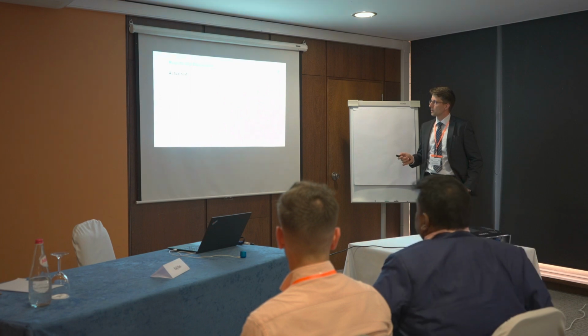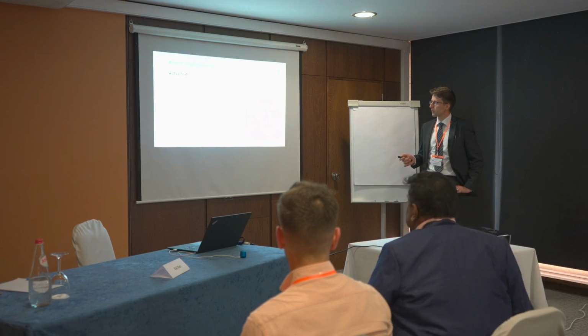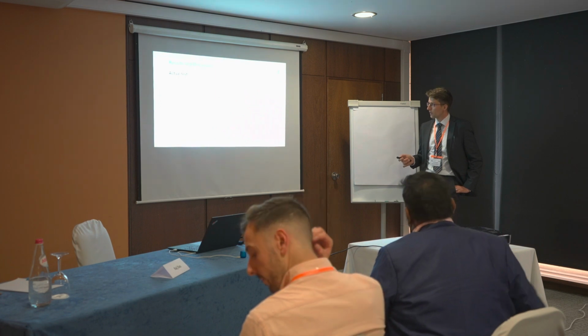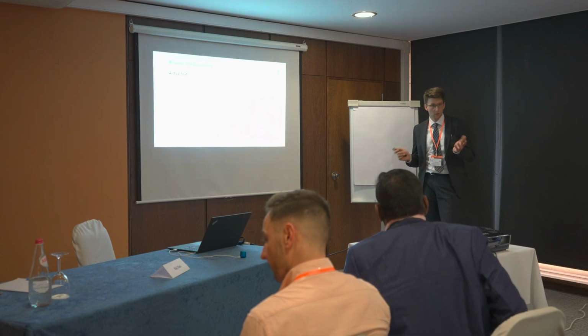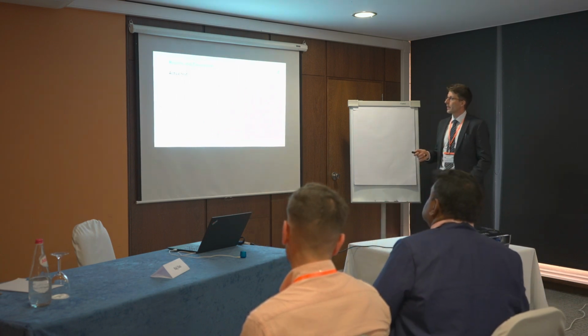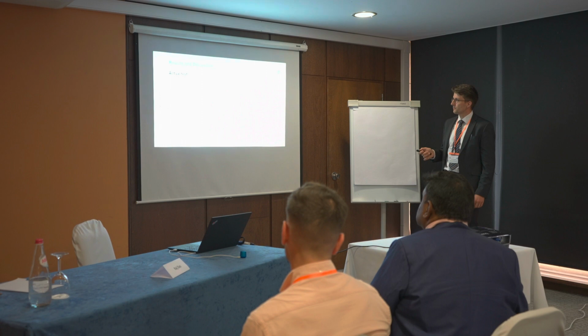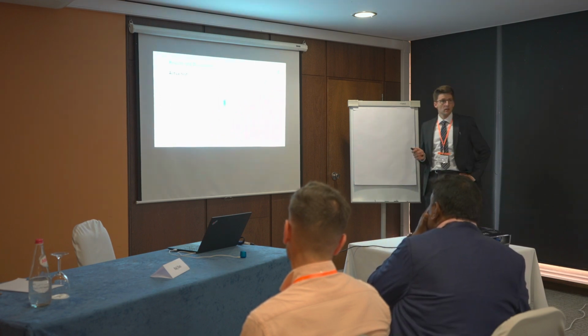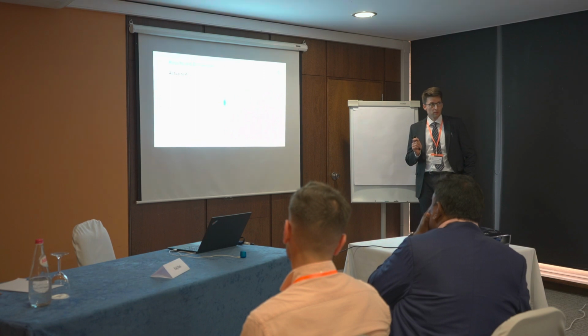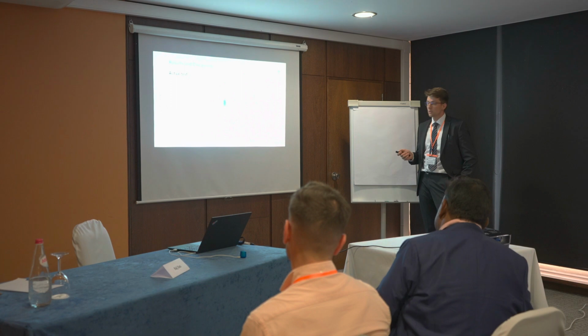Then we performed an actual test with the known calibration constants. We also use a smaller pulse shaper. We introduce this incident pulse. When we use a specimen, we of course get a reflected pulse and the transmitted pulse in red. And then we can compare the displacements measured by the optical extensometer and the calculated displacements with the known calibration factors.